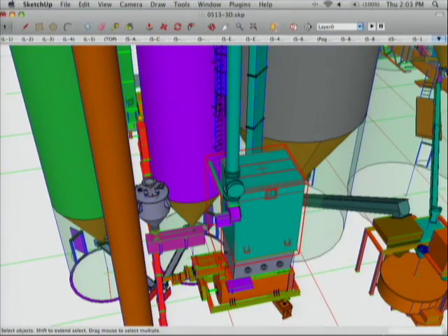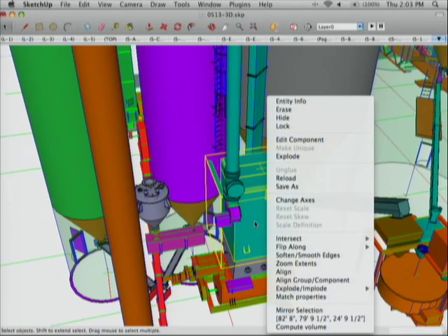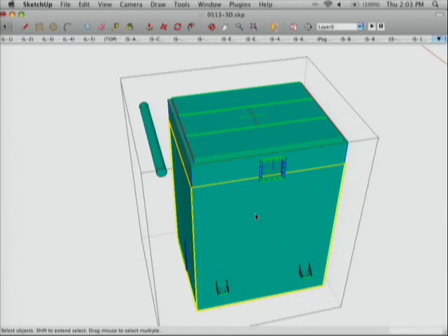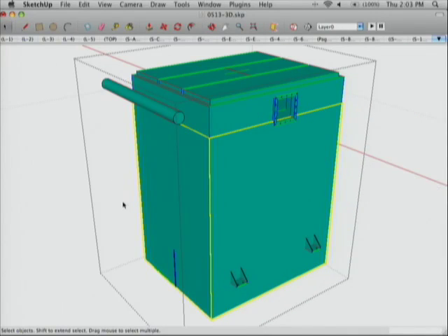Face hints. Using X-rays, wireframe, I talked about before. I'm going to demonstrate hiding the rest of the model. And again, in the help menu, there are instructions on how to use the move tool with absolute and relative addressing. Most people don't realize they can do that in SketchUp. So I'm going to have to unlock things here. If I come into this piece, every other part of the model goes away. So if I zoom extents, I'm there. Or I can go back and turn on the rest of the model. I'm going to wait as the rest of the model comes on. There it goes.